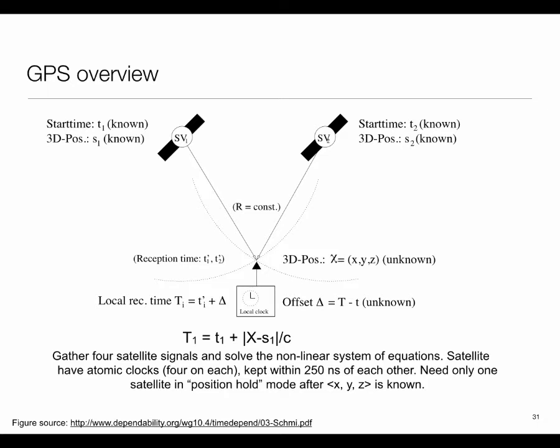Now, to measure the travel time, in effect, they first have to estimate time here. So the equations that get solved are in 4 variables: x, y, z, and t. And locally, these GPS receivers use some stable clock source, usually a TCXO, because otherwise, as you make multiple measurements, the standard crystal oscillators are too drifty to get you an accurate location. That is one of the reasons TCXOs are used.